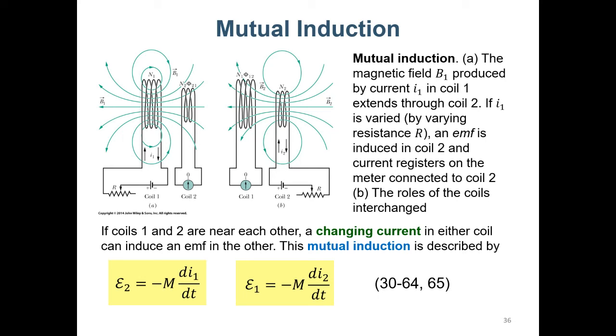Actually, that's what I just mentioned. I just mixed it up. It should be the mutual inductance, not the self-inductance. Self-inductance is an inductance of the coil itself. This should be the mutual inductance. So in this case, coil one has a changing B field. This changing B field will generate a changing magnetic flux for this coil, and according to Faraday's law, this changing magnetic flux will generate an induced EMF.